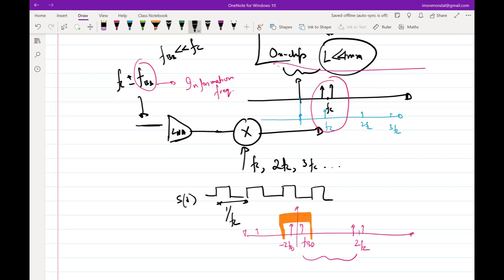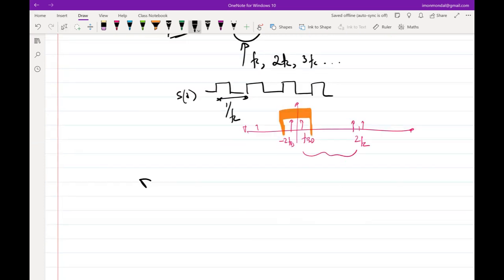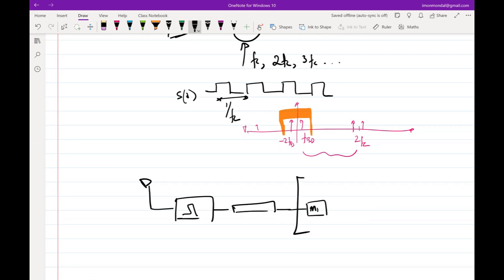So which naturally means that the architecture evolves to: you have a SAW filter, your transmission line, you are inside that, you have a matching network, you have an LNA, then you have a low pass filter. Sorry, I have a mixer.